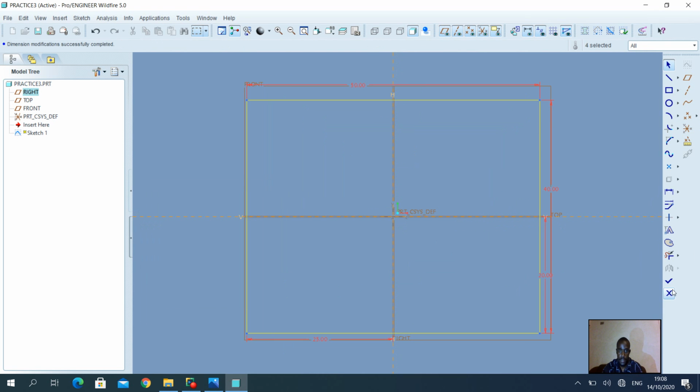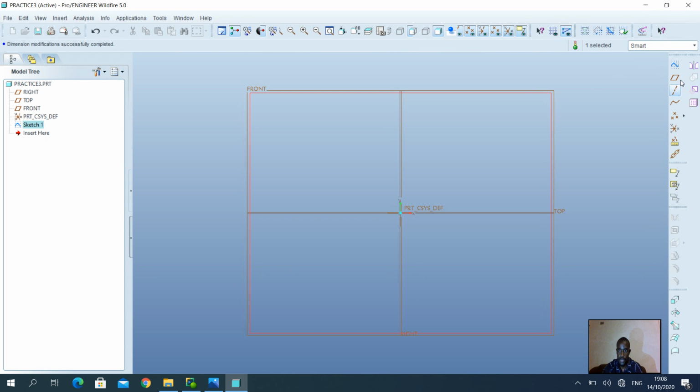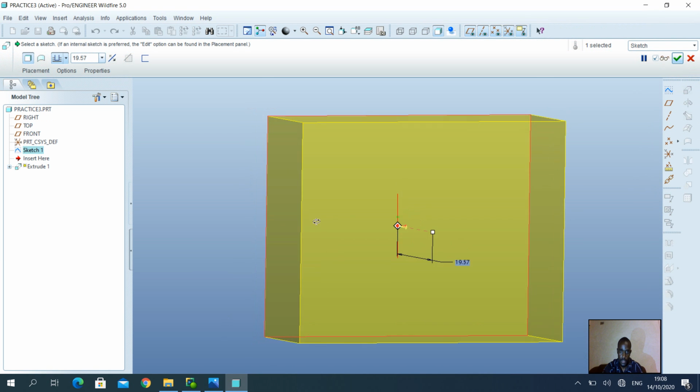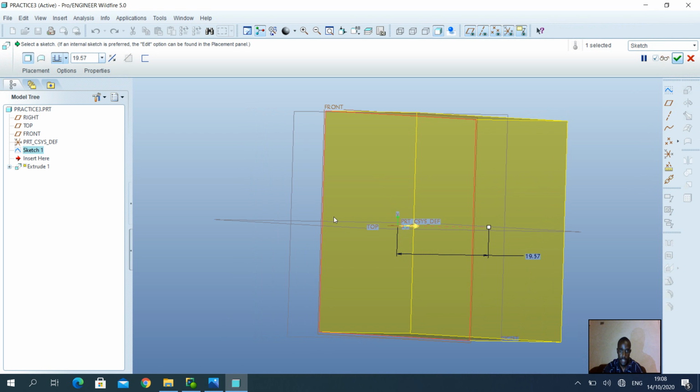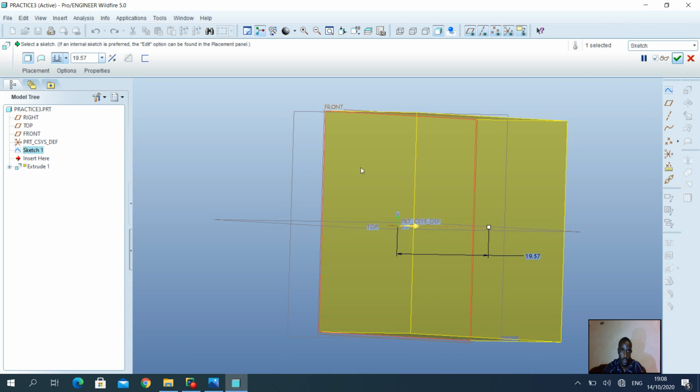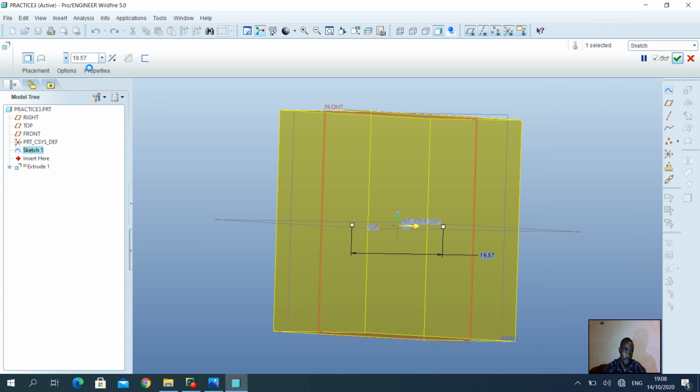That's your rectangular block, which I'm going to be extruding to a distance of what? So let me see how this thing is extruding. And as expected, by default it adds material on one side of the block, and I want an extrusion distance of this amount. Where do I get this total side, which is 12 plus 12 plus 12? That is 36. So I'm going to be extruding on both sides. I want to make the front plane central. So on both sides of the plane, and extrusion distance of 36.